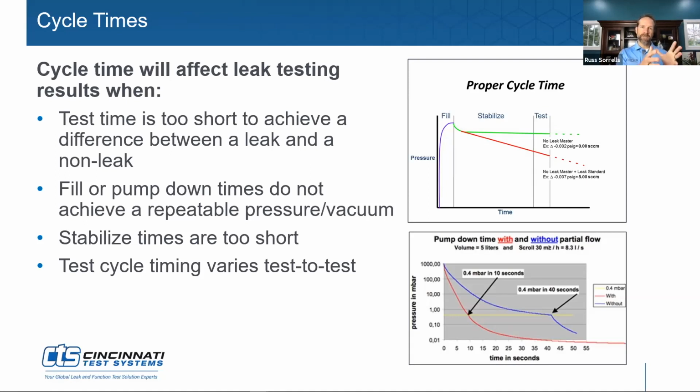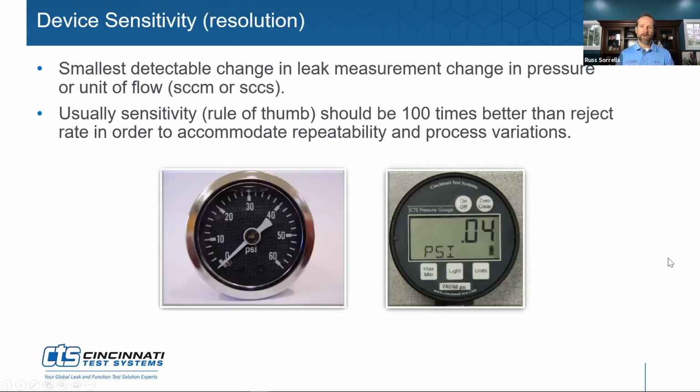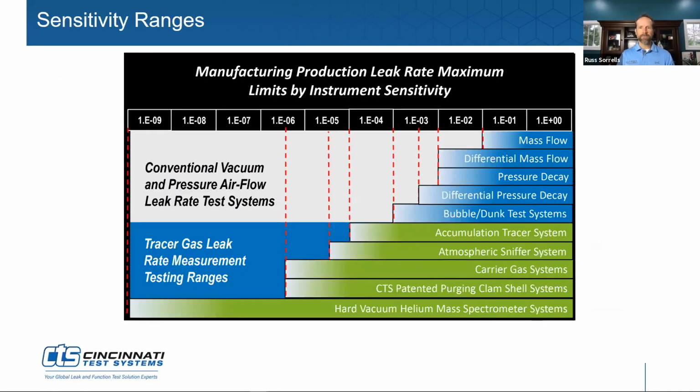You want to make sure that your test pressure is set prior to connecting up and starting to identify what that appropriate fill time is for your application so it reaches that target pressure. So does that answer that question? And then one thing we didn't talk about, and of course we're going to talk about this more in Pressure K, is the stabilization. How do we determine whether a part is stable? We're going to get into all of that as we continue through here as well.